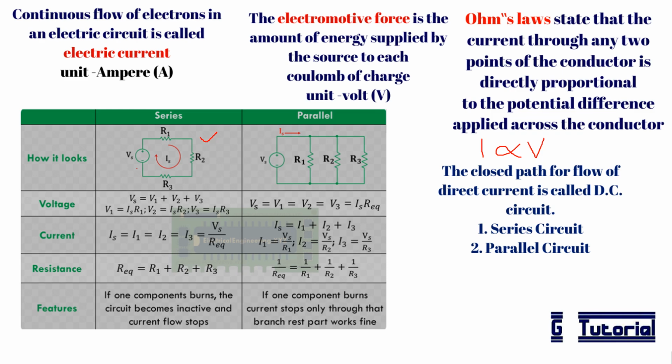So we can see the case of two resistances. If there are only two resistances, then we can simply say that R equivalent will be equal to, substituting for 1 by R1 and 1 by R2 and solving, and taking the reciprocal, we will get R equivalent is equal to R1 into R2 divided by R1 plus R2. This is one of the important formulas.